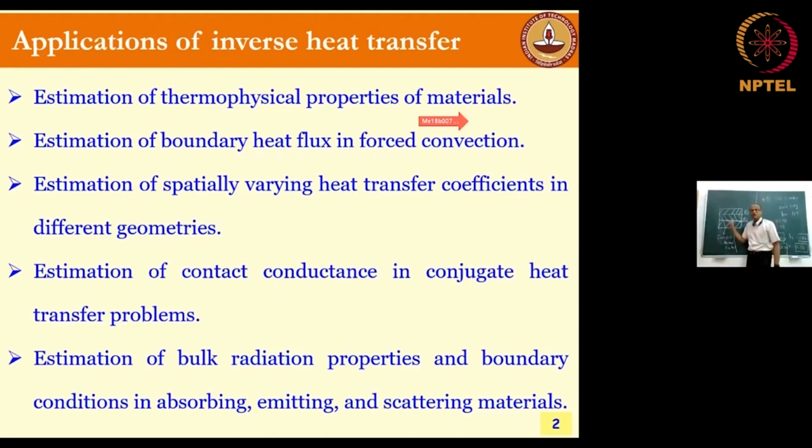And then you figure out that the heat transfer scientist in the heat transfer group forgot the contact conductance. So they are asking about a sensor, something has to be measured and something is malfunctioning. Then the problem could be that you did not estimate something. So simple heat transfer, no? If the heat transfer group is doing the calculation, they will say these are all 3 resistances in series. KA, KB, KC, LA, LB, LC, then you will do all that, right? So you know how to do it.